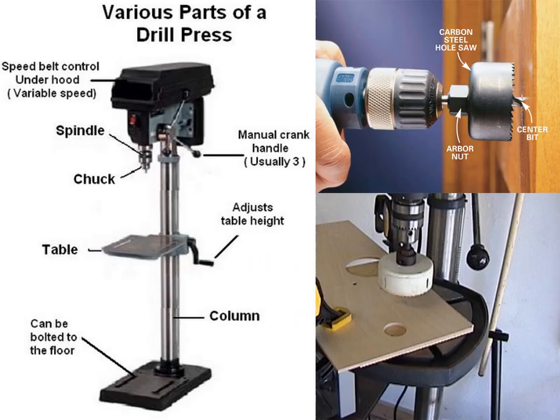So this shows a drill press. Drill presses are nice because they give you nice, perfect perpendicular holes. They're also really nice because they usually have some sort of speed control that you often don't get on a hand drill. And they're a lot more sturdy, and they can do a lot more than a hand drill can, or do it a lot cleaner.